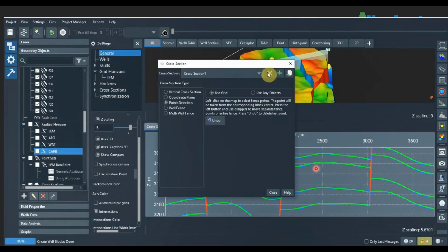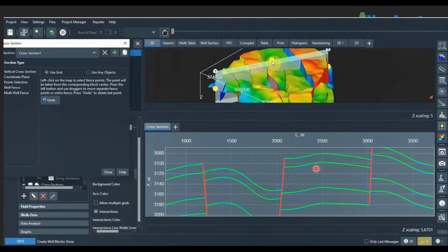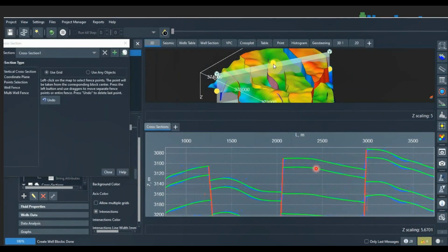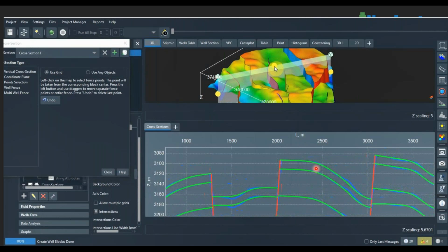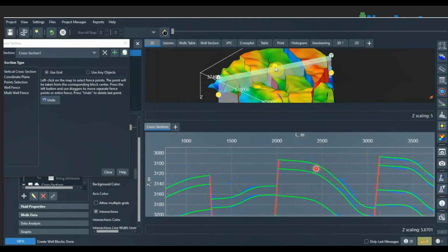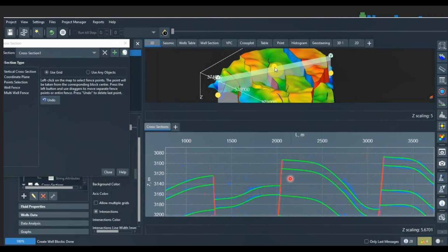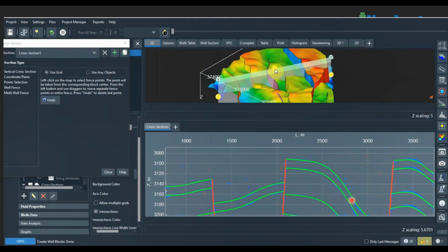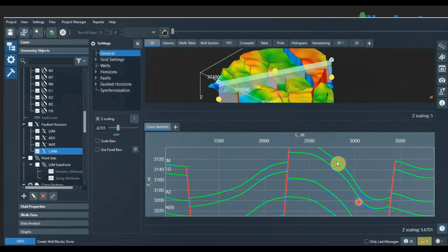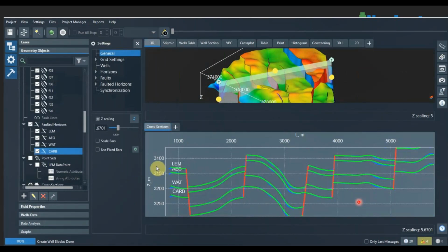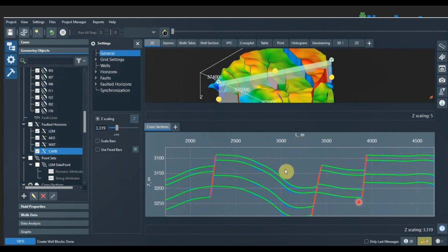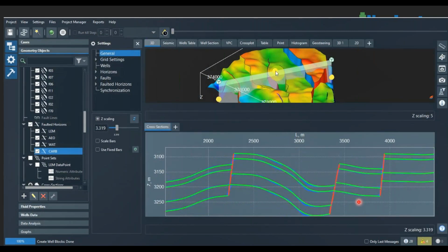So it's a very advisable way of creating a 3D grid where you can honor the faults and also have a clean area around the faults. If you see some difference here, you can always go back and edit it later, right? But at least before you start with the property modeling distribution, make sure your structural map is honoring your input data.